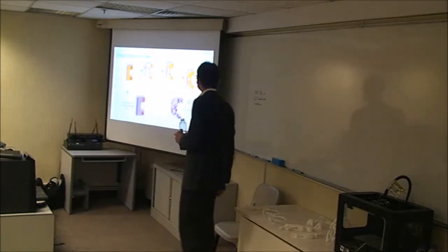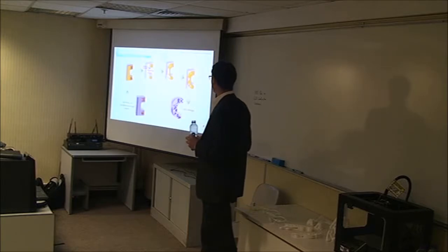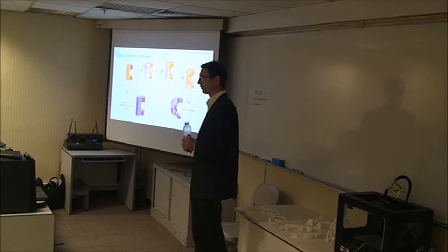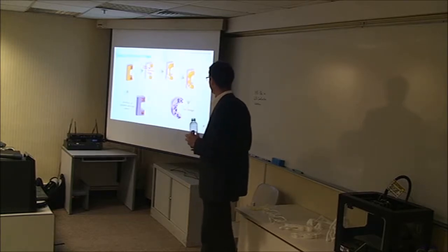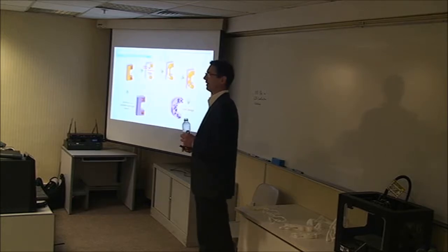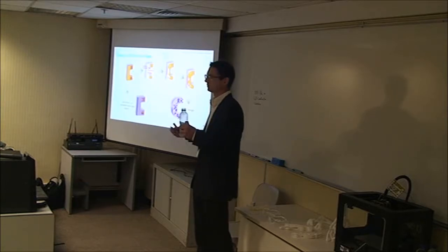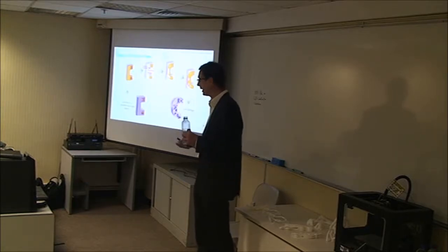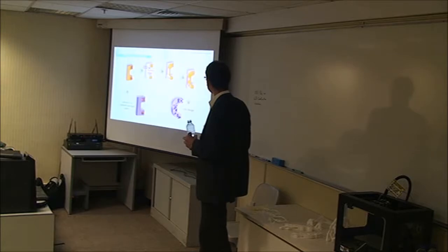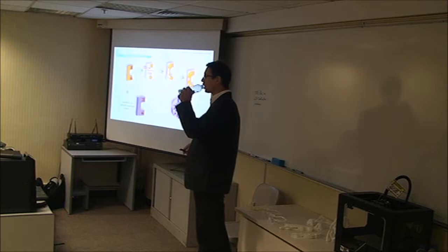Here is another step-by-step graph. You define the possible workspace, how big the part can be. Then you define the forces which will act on the part. You define the target: stress, stiffness, weight, whatever you want to define. You can define a lot. And then the computer step by step calculates where the material should be.